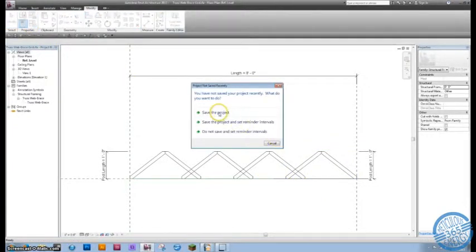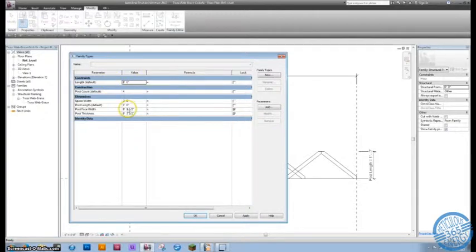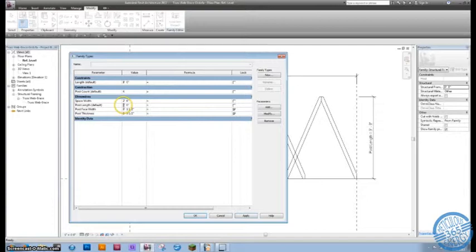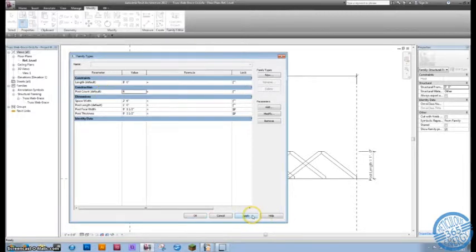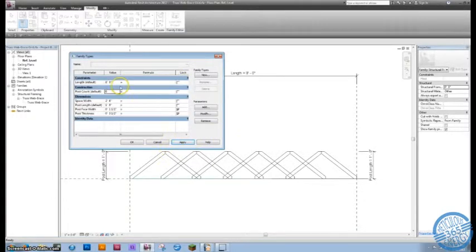I can change the width of these elements if I need to, and they get fatter. The thickness is in a direction you can't see from this angle. I can change the height of them to 3 feet, and they will all morph properly in their arrayed fashion. The count is currently 4. We can set it up to 6, and more of them will show up. So this array is already ready to go.